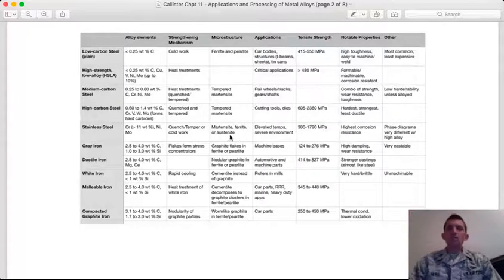Even though you're used to thinking about austenite as a high temperature microstructure that transforms, you can so distort the phase diagram through the alloying elements that you lower the austenite region all the way to room temperature. But the stainless steels get their name from their high corrosion resistance.